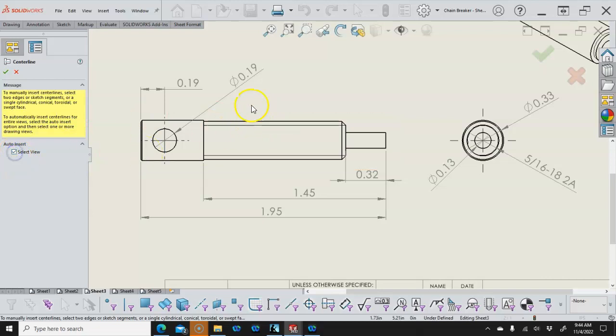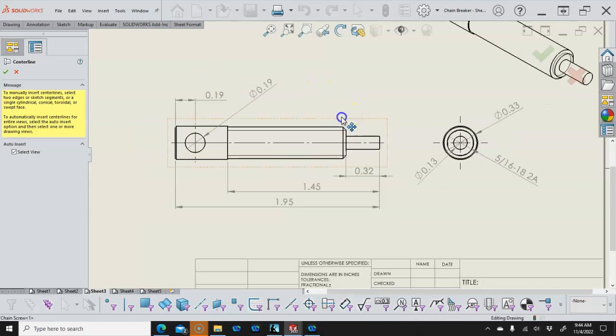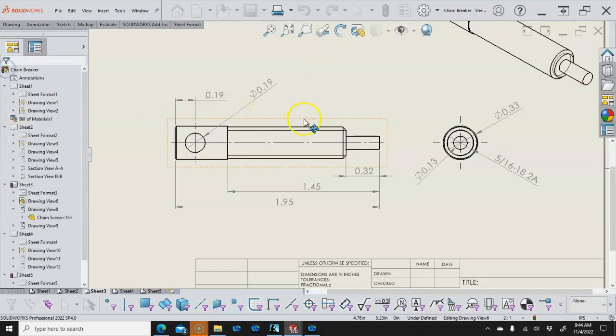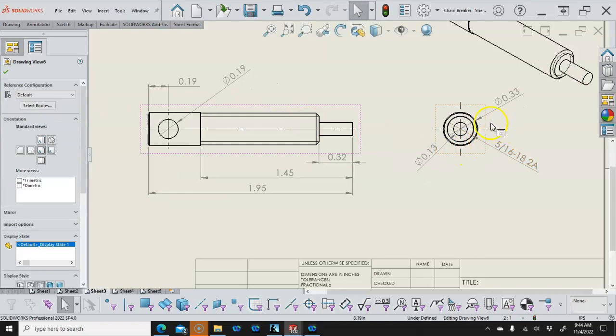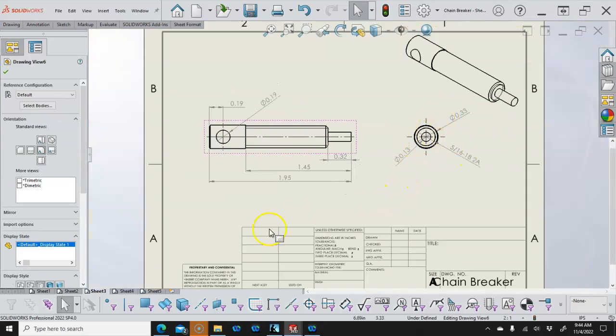Maybe we can select the view. All right, so it pretty much says everything's on the same center line. That one's centered, and the distance off of the end. The rest of our numbers come off of that edge. So from a manufacturing standpoint, if I'm making this manually or even if I'm making it with the CNC, I have numbers that are realistic to what I'm generating.